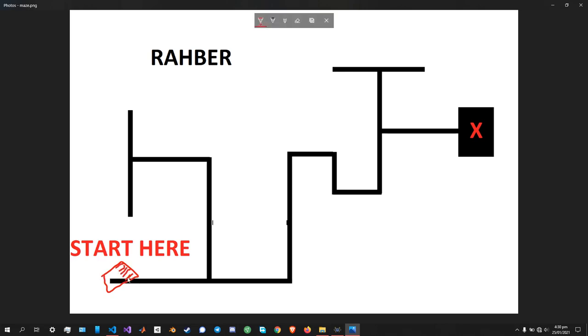The rightmost sensor is gonna change its status, if you remember the status that we talked about a while ago. So the rightmost sensor is gonna go from no line onto the line and then off the line, when it's turning counterclockwise. So the sensor is gonna go from status of 0 to the status of 1, and then again the status of 0, right?